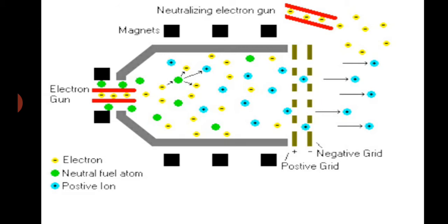Electrons are emitted from the hollow cathode tube, which is also known as the discharge cathode. These electrons enter the magnetic ringed chamber, where they strike the xenon atoms. These electrons hit the electrons of the xenon atom, as it consists of 54 electrons. This results in the formation of ions in the discharge chamber.